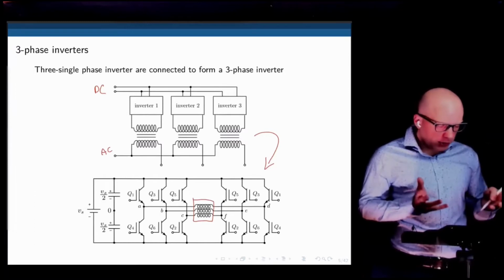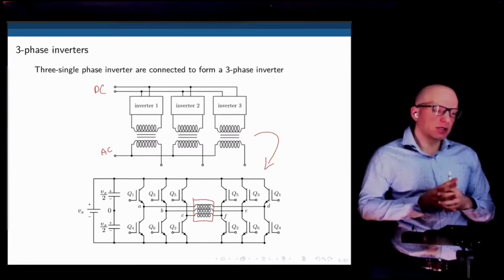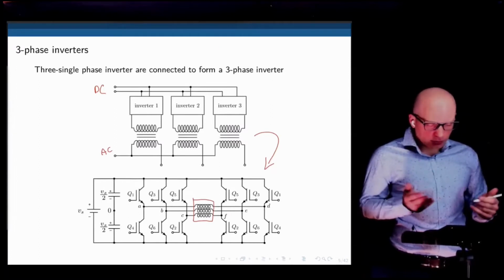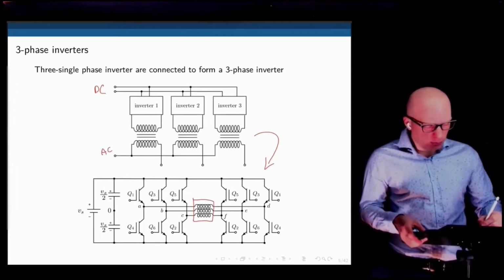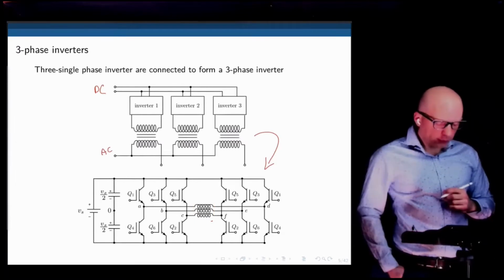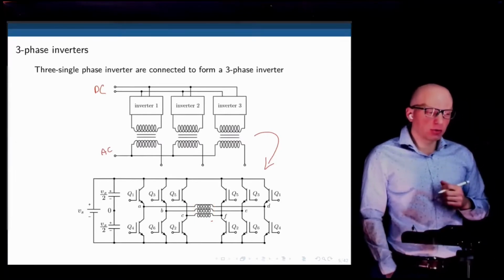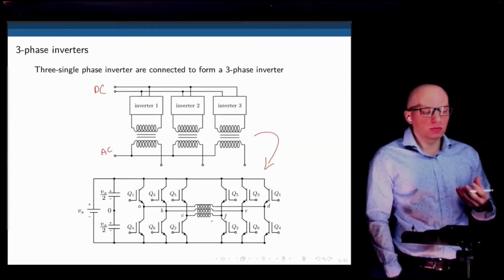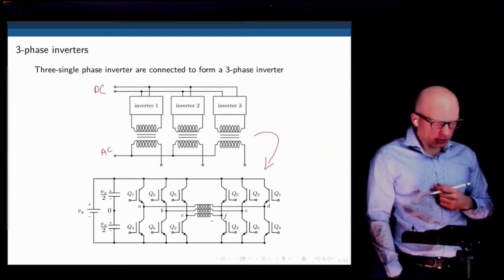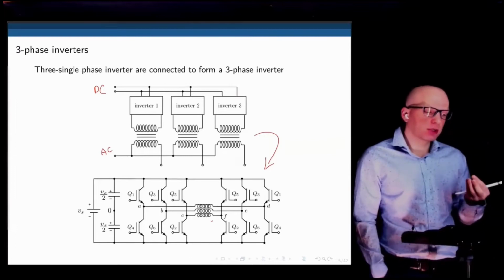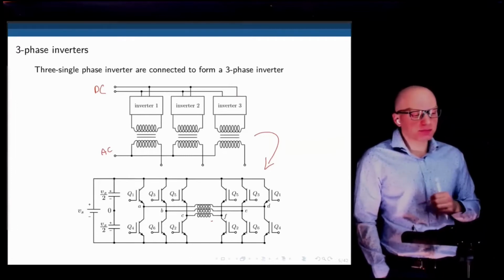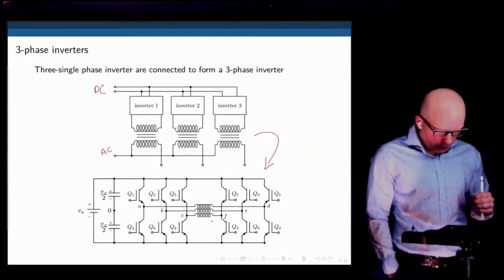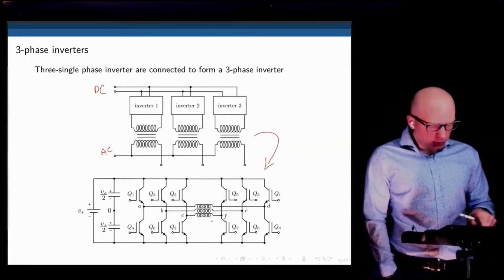The problem with this arrangement is that timing the signals is challenging. It needs to be very precise. And another potential challenge here is the fact that we would need 12 transistors, 12 diodes to create this 3-phase inverter. So the cost is significant, and also physically to implement the timing between the gates, the gating signal, that would be relatively complicated. So what is the better solution?